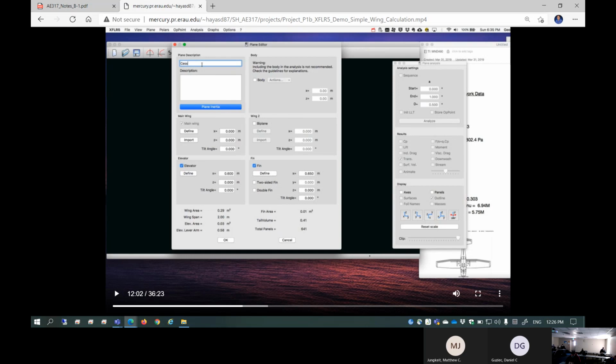Once you complete your 2D database building, this airplane only uses a single NACA 4-digit foil, NACA 2412. Using that database, you're now going to design your wing. Without your database, you can never design anything, so be careful about that. You begin with the 2D analysis first, and then you can actually start designing your own wing.